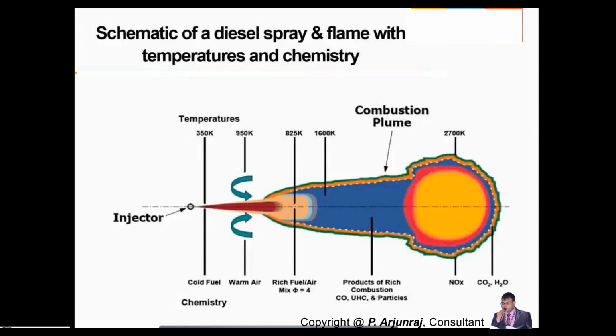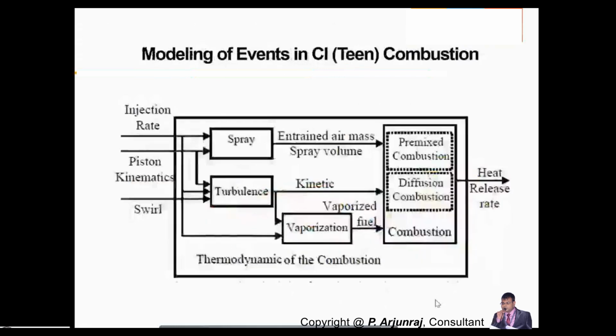But this reduced nitrogen oxide emission will also lead to high particulate matter. Okay, so again there are pros and cons. So it's always best to go for multiple injection strategies.